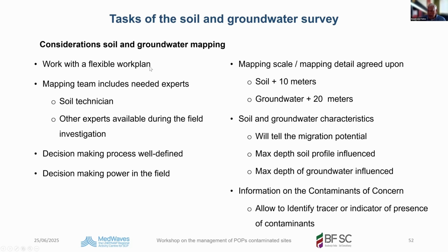Work with a flexible work plan. So you may come across unexpected things, so you should be flexible in time and flexible with your resources. Have enough material with you, have enough financial resources to extend your survey with 1 or 2 days. The mapping team includes a soil technician and other experts available during the field work, meaning that if you come across difficulties related to groundwater, you should be able to consult someone who is a specialist on groundwater survey.